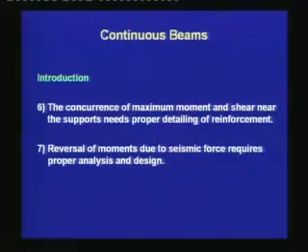The seventh disadvantage is that reversal of moments due to seismic forces requires proper analysis and design. I had mentioned earlier that in high seismic regions, continuous beams are preferred because they have redundancy within the structure. But if we are designing a continuous beam for seismic forces, then there are chances of reversal of moments, and in such a situation it has to be accounted for in the analysis and design.